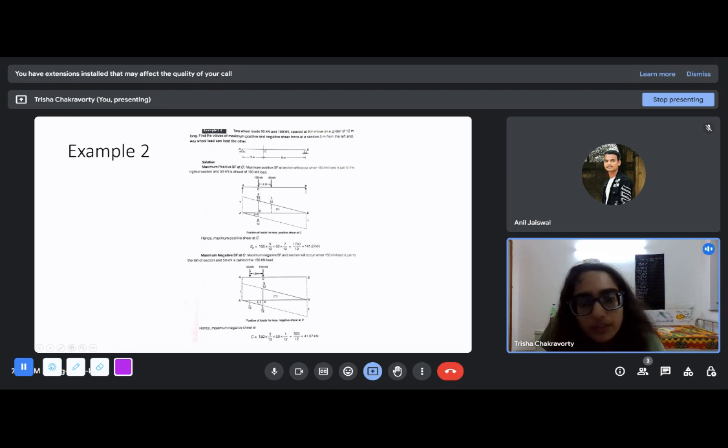So if you put the 150 kilonewton at this point, you will find the worst positive shear force. So we will put the 150 kilonewton just to the right of C, and the 50 kilonewton on this side. Why are we putting the 50 kilonewton on this side? Because if you put it on that side, this will cancel out. Like if the 50 kilonewton has a negative ordinate, it will be 150 into 9 by 12 minus some value.